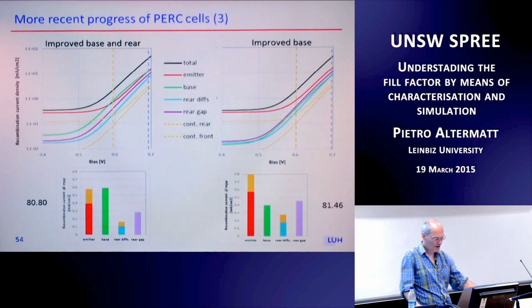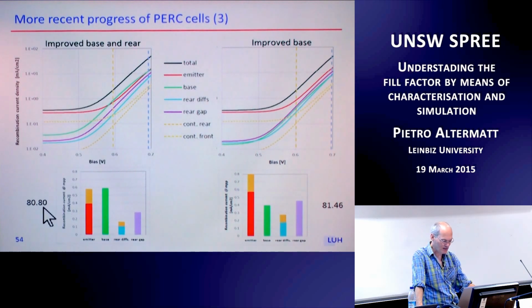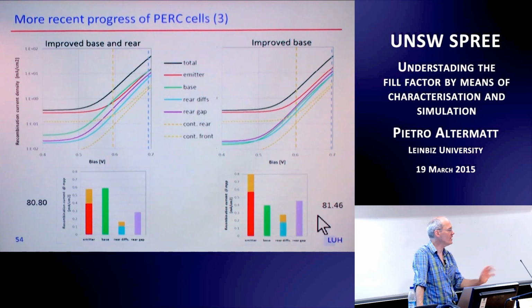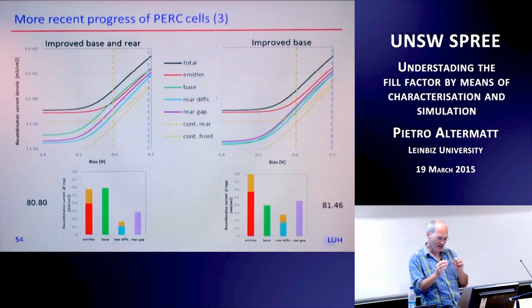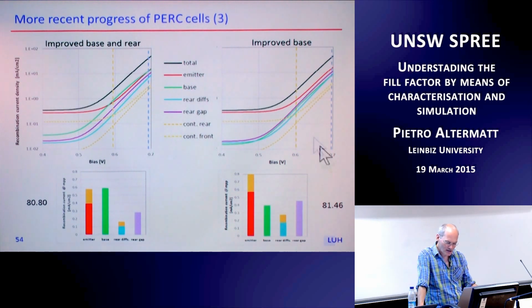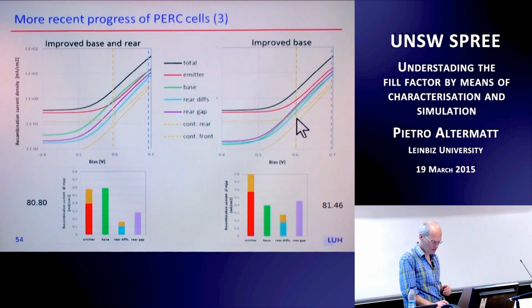And that's why you got quite a big increase in fill factor compared to the previous ones. Yeah? So designing a PERC cell is basically a very intricate kind of juggling between the losses along MPP here. And that determines your roadmap of a PERC cell, of what you should do next.